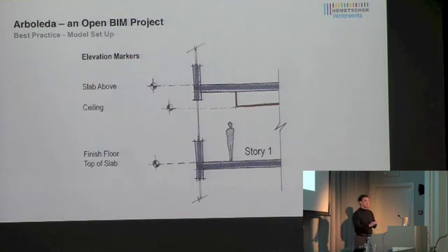So we understand that stories is all about control of heights, and this sketch started everything. I needed to know my top slab. I needed to know my drop ceiling as part of the project, because my pipes and my ventilation will go right in between the slab and the ceiling. So I only have 3 levels of control, just so you know that.